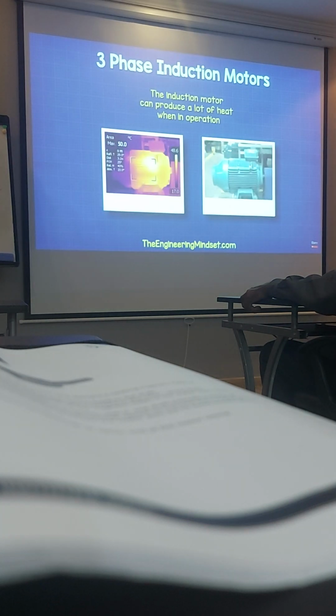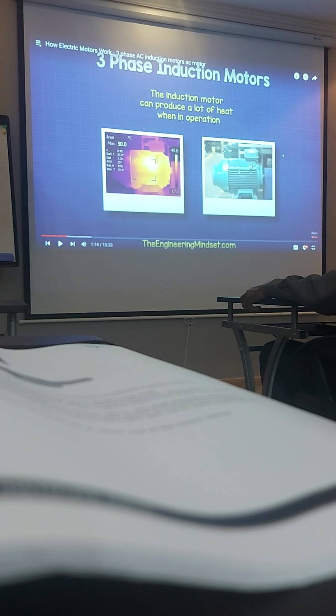That's because of the induction motor. As I told you, when the induction motor is continuously driven in industry, 24 hours a day, 7 days a week, the motor gets very hot. So to avoid that we use the cooling fan. The second reason for the motor to get very hot is starting current. Whenever the motor is starting, the current will be very high.